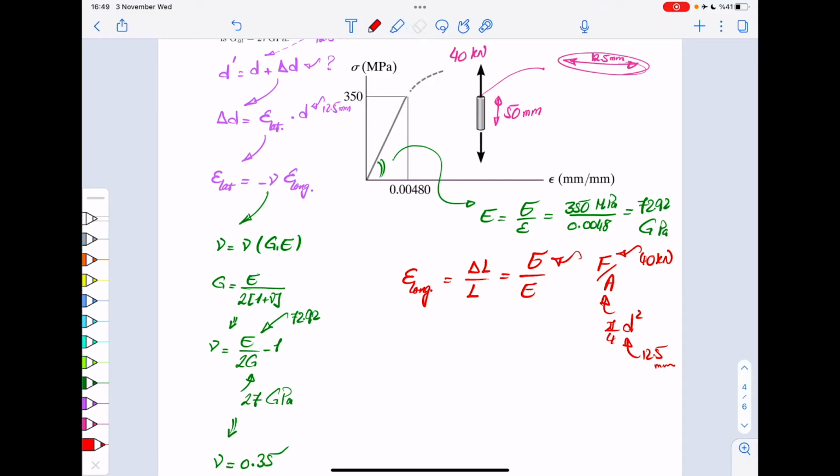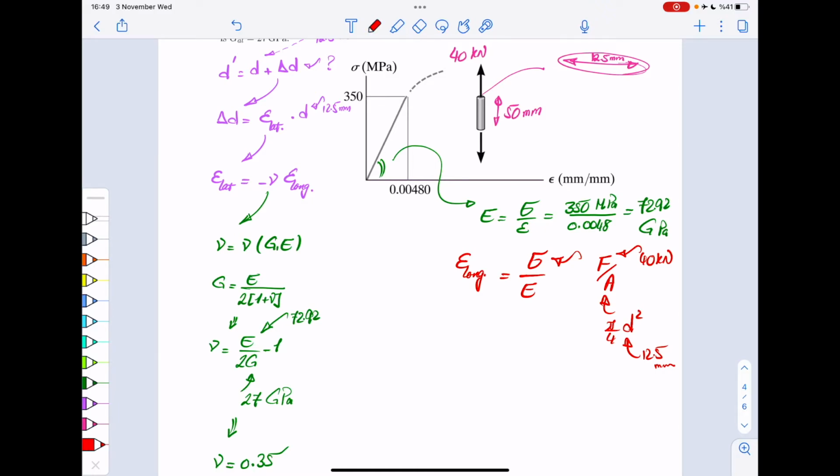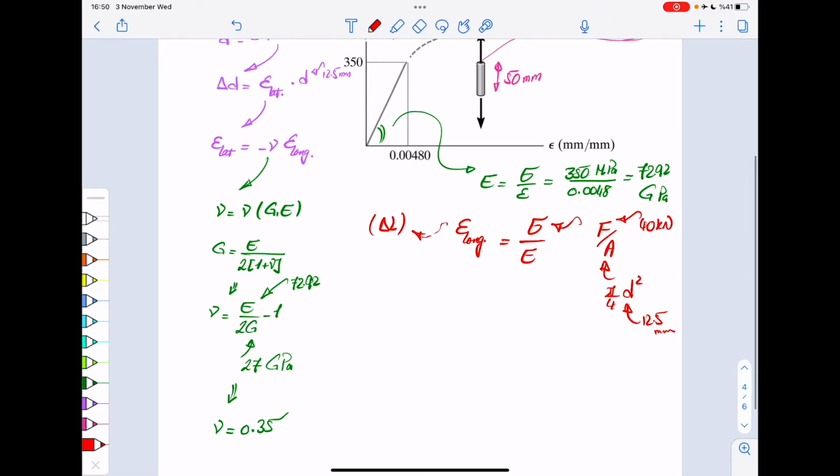As I mentioned, usually in this sort of problems, we are looking for something like this, but in this particular example, we are not even asking you for that. You just calculate the longitudinal strain from the relationship you have. Again, from that relationship, obviously, you can calculate delta L if you wanted to. But we are not asking you about that. So the problem makes it a little more complicated. Anyway, from this, now you have 40 kilonewton, you have pi over 4 d squared, so you can calculate that stress that you apply.